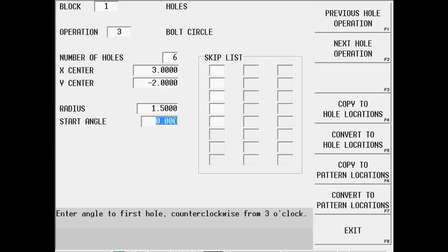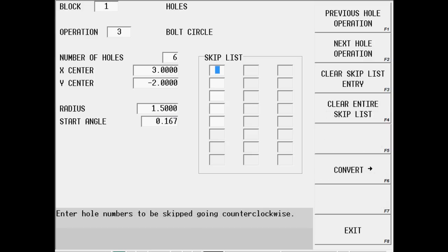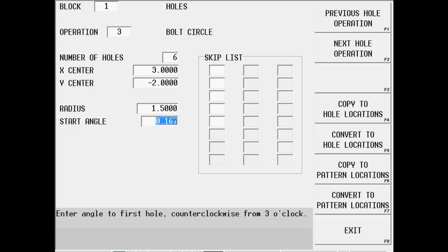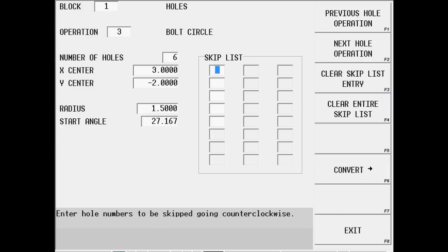In this particular case, we only have one that can be determined, and that is 27 degrees and 10 minutes shy of 270 degrees. So what we're going to do is first figure out what that 10 minutes is. If we take 10 divided by 60, so 10 minutes divided by 60, we get a decimal equivalent of 0.167. Now I can add 27 degrees to that, 27 plus enter, and that will give me the decimal equivalent of 27 degrees and 10 minutes.